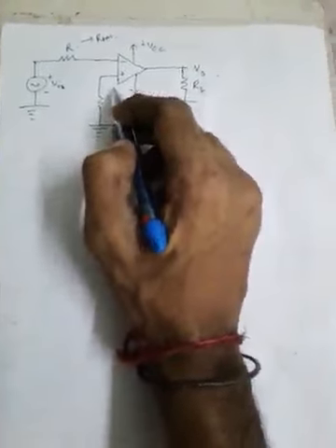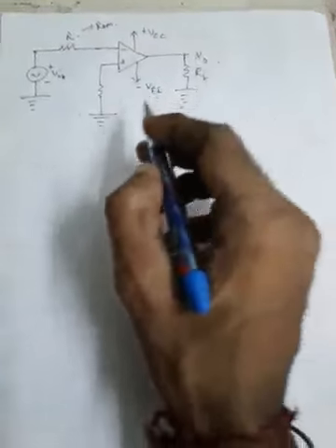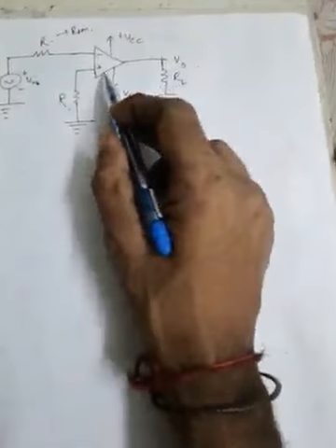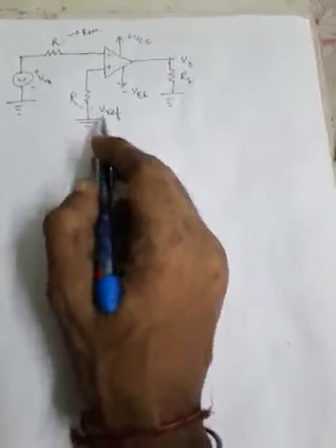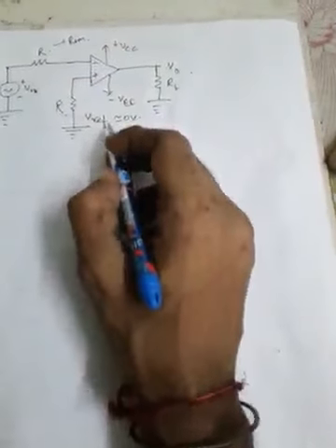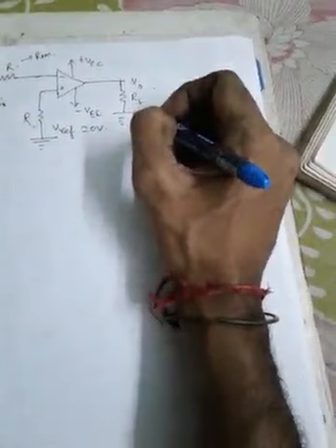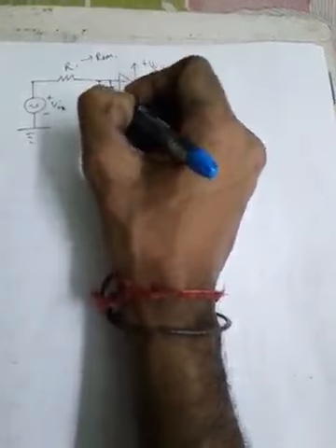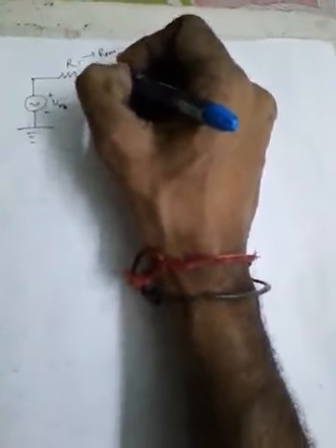So obviously this is a basic comparator in inverting mode, and this is R that is connected in the non-inverting terminal. The point to be noted here is that there is no Vreference DC source shown in this circuit. So therefore Vreference is considered here as 0 volt. So this is 0 volt, and this is the load resistance RL across which the output voltage is seen. The protective diodes can be drawn like this, as usual. So these are protective diodes.